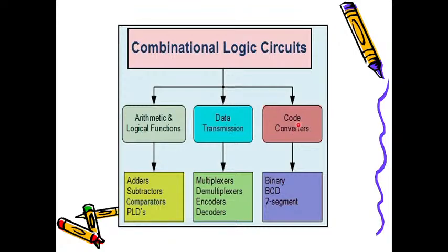What are the different codes? You have positive codes, negative codes. Under positive codes, you have the 8421 code. 8421 is the code used for BCD representation, and the extensions of that, that is 1 2 4 8 16 32 64 128, we just listed based on 2 power n, because that is also one set of codes which could be categorized under binary.